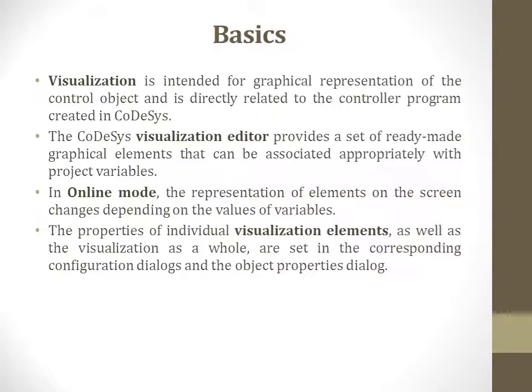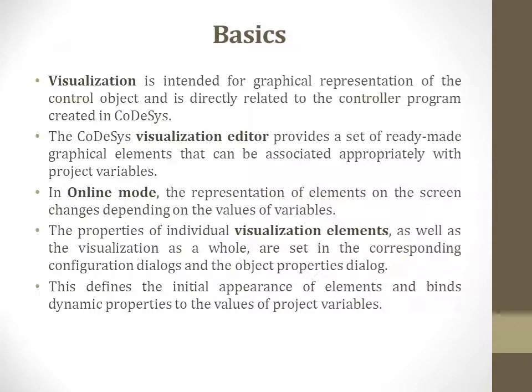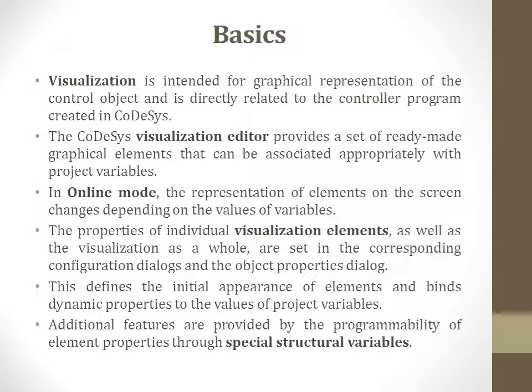The properties of individual visualization elements as well as the visualization as a whole are set in the corresponding configuration dialogs and the object properties dialog. This defines the initial appearance of elements and binds dynamic properties to the values of project variables. Additional features are provided by the programmability of element properties through special structural variables.